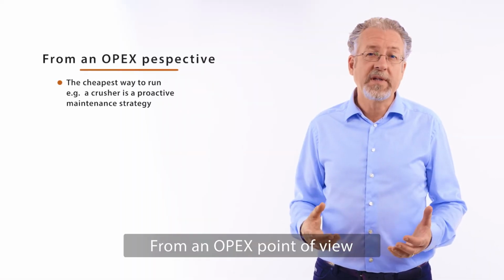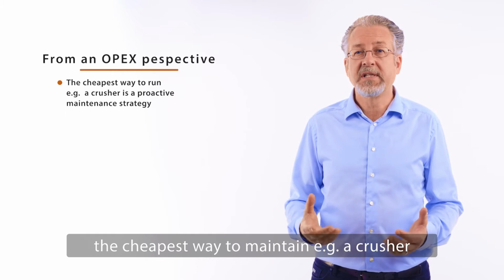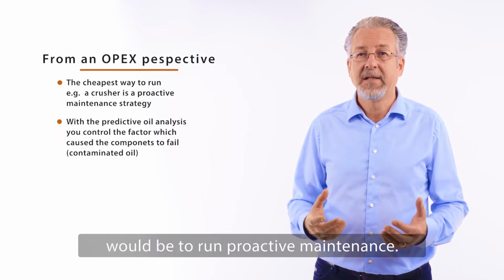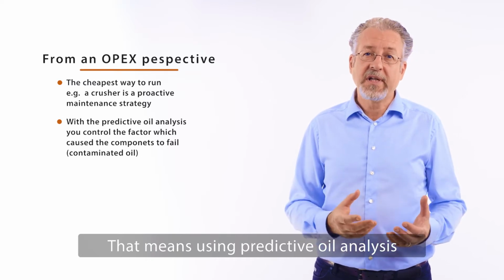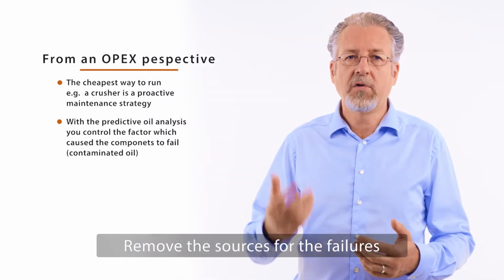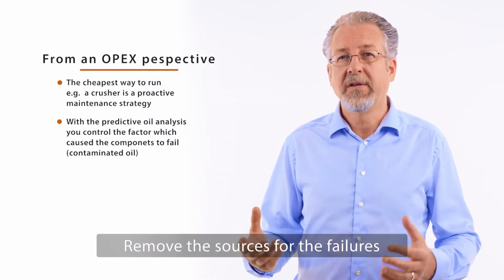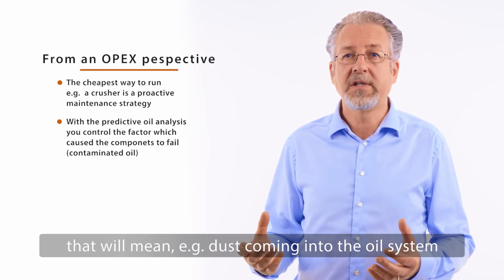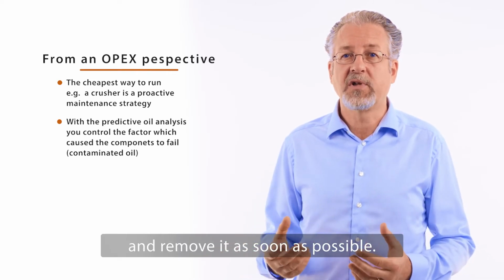So from an OPEX point of view, the cheapest way to maintain, for example, a crusher would be to run proactive maintenance. That means using predictive oil analysis to monitor the oil cleanliness, also remove the sources for the failures. That will mean, for example, dust coming into the oil system, and remove it as soon as possible.